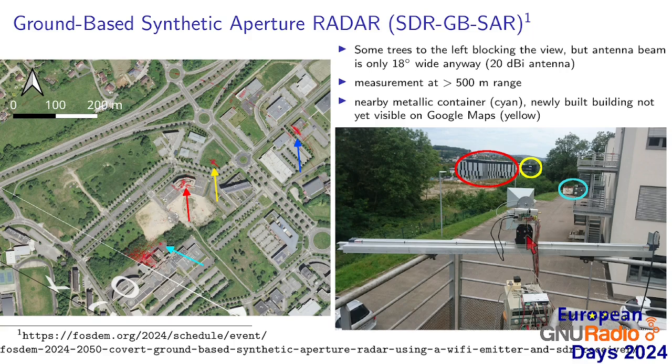The control of the antenna is under supervision of a Raspberry Pi, which receives orders from the PC collecting the data. So the PC is continuously receiving data, only stores them if the antennas are at a known stable location, sends a command to the Raspberry Pi to move by one step, waits until the antennas are at a fixed location, and then collects the new data.